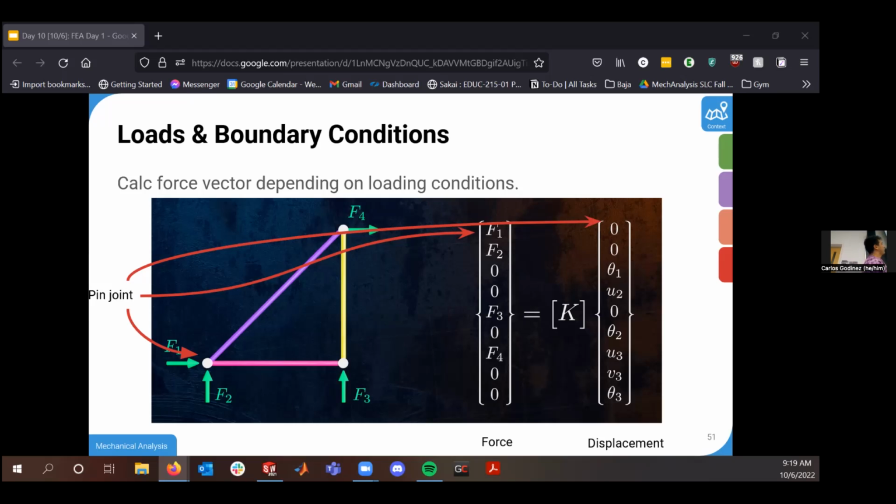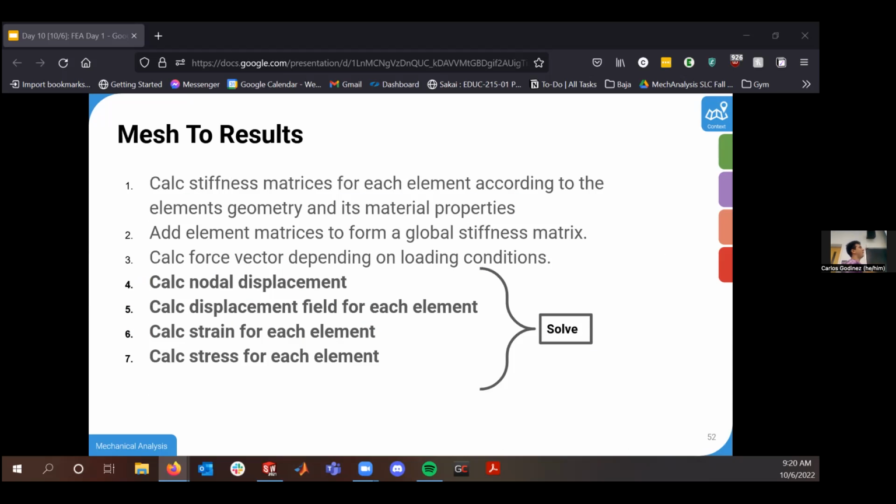And in my Y direction for my displacement, I'll have 0 because it cannot move in that direction. And lastly, F4 is just the reaction force that's being pushed on it. So again, this basic idea comes from you just set up a system of equations F, K, and U.